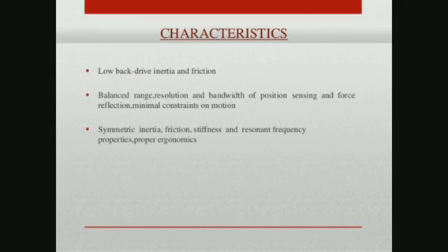Characteristics. Characteristics commonly considered desirable for a haptic interface device are low backdrive inertia and friction, balanced range, resolution, and bandwidth of position sensing and force reflection, minimal constraints on motion, symmetric inertia, friction, stiffness and resonant frequency properties, and proper ergonomics.